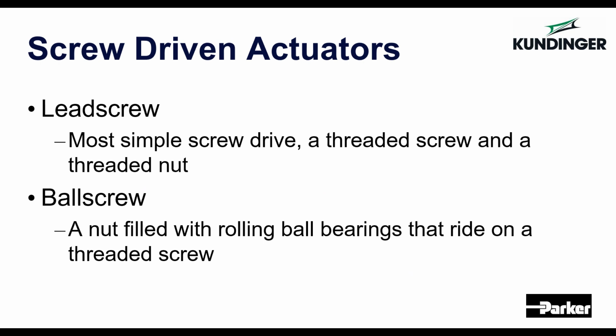The advantage with screws, any type of screw drive, is that it does add an inherent mechanical advantage for the motor, reducing your reflected torque and your reflected inertia. So something like a belt drive, for example, is not going to put any kind of mechanical advantage to the motor, so you may end up needing a gearbox to make that work.